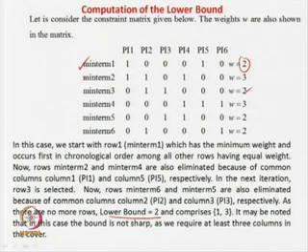Then we take the first row and say that we select this row. How do we select this row? It may be selected by this one or by this one. And why have we started with the minimum number of ones? Because that is more difficult to cover compared to the other case where there are more ones. Now, if row number 1 is covered by Pi 1, then automatically minterm 2 gets covered, right? And if you cover it by Pi 5, then minterm 4 gets covered. So, it is saying that if you take row 1, there is a very high chance that minterm 2 or minterm 4 will be covered. So, it is actually cutting out these 2.